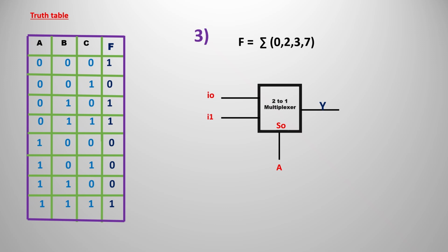Before seeing the truth table directly, we are going to understand the basic concept behind it. For that, I am taking a random logic where F is our output. We generally go from 0 to 7, and the output expression contains minterms 0 to 3 and 7. First we are going to implement these three variables. As we have three variables, we could implement with any of the three methods, but we are going to follow the third method for better understanding.